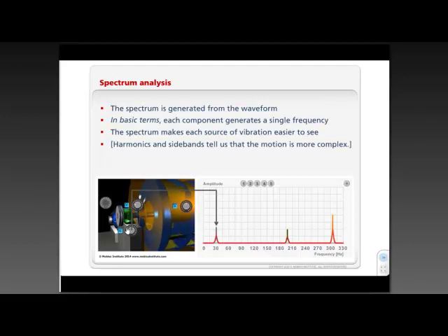We'll generally have a peak, but as the unbalance, let's say, gets worse and worse, as dirt builds up on the fan, we get a higher amplitude peak at the running speed. This is the running speed of this little simulated machine. It is 1 times the speed of the machine. We often call that the 1x peak. And down here, let's say we've got, I forget now, 14 blades on this fan.